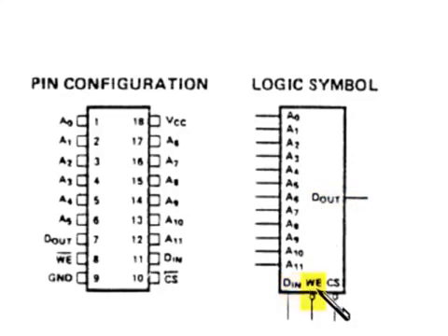Now we've got a WE command, and if you read that, that's called the write enable. When that goes low, we're writing to the chip, which means we're sending data into the chip. So when you make that line low, the chip select, of course, has got to be low just to make the chip work in the first place.